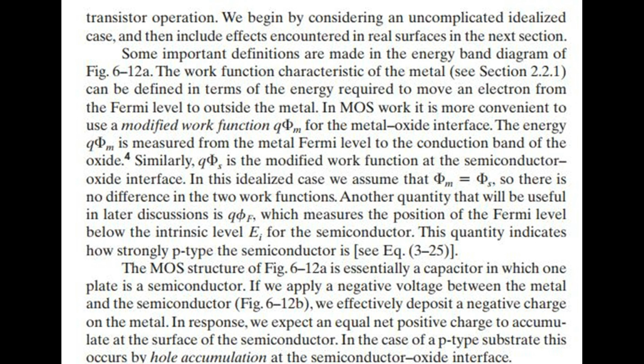In this idealized case we assume that Φm equals Φs, so there is no difference in the two work functions. Another quantity that will be useful in later discussions is qΦF, which measures the position of the Fermi level below the intrinsic level Ei for the semiconductor. This quantity indicates how strongly p-type the semiconductor is.